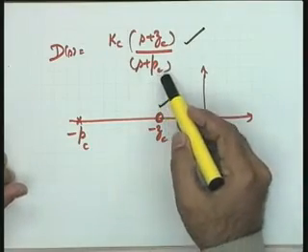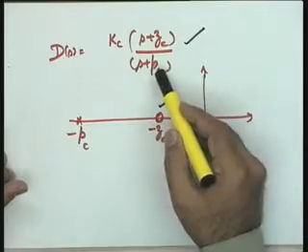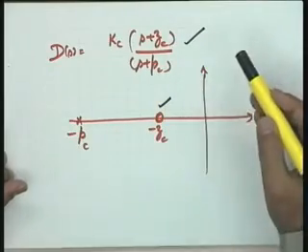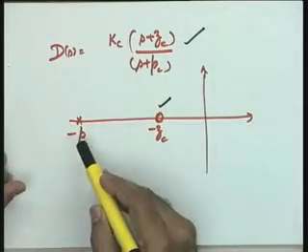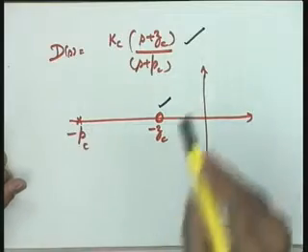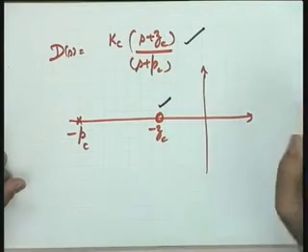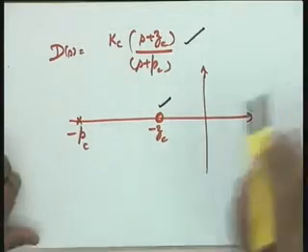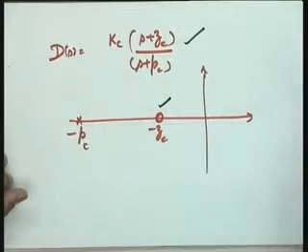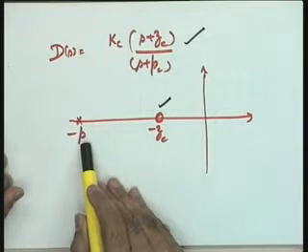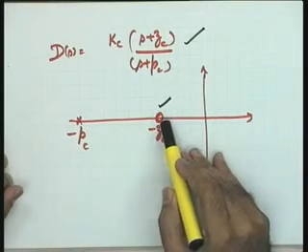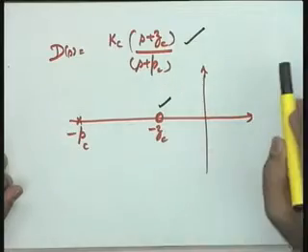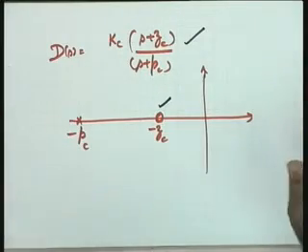If I remove this particular pole, this is the transfer function of a PD compensator. I am introducing a pole over here to take care of the additional noise filtering requirements. So if I ask you for a design of a PD compensator, you can forget about this pole. In that case, I want you to place the zero appropriately so that all the performance requirements are satisfied.